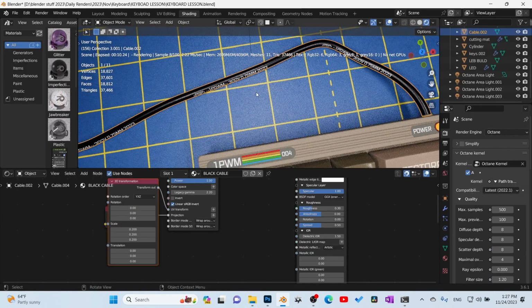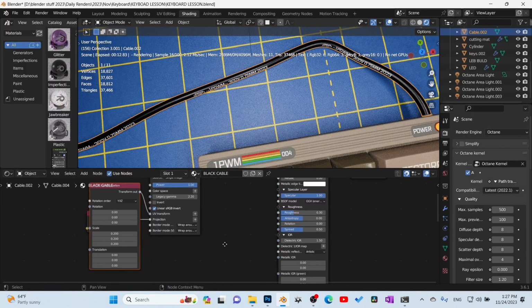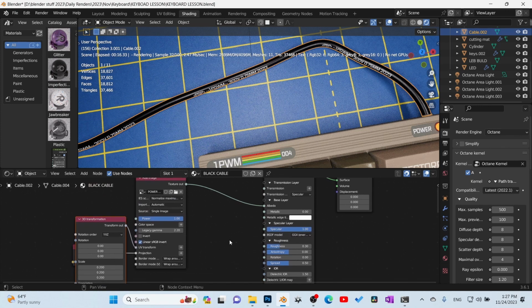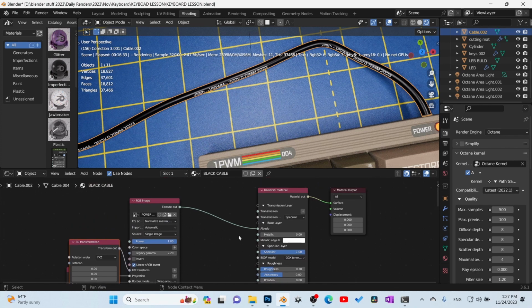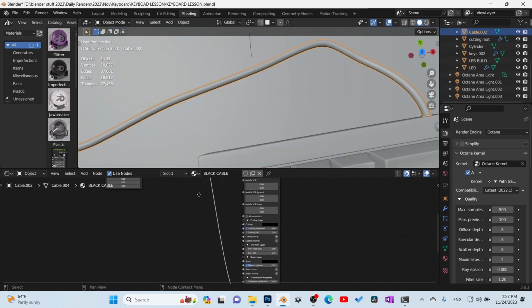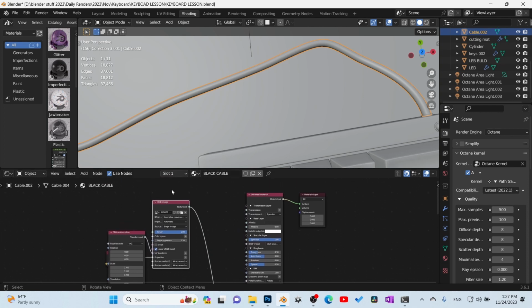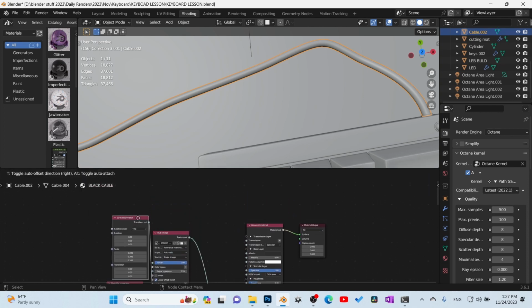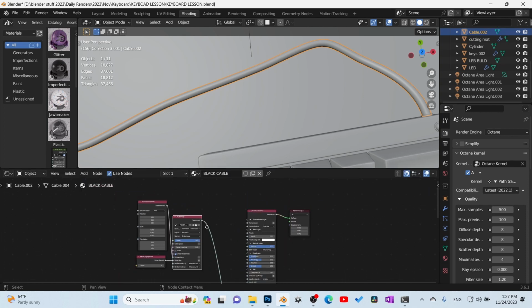Now you could leave this like that if you really wanted to show it off, but I'm going for more of a real light, and it's actually black and it's embossed, right? So what we do is we just use this here so we can see it, and then we'll plug this into the bump. And then while I'm at it, I'm also going to add in just a little bit of a roughness map so we don't have it perfect. Go ahead, Shift D, duplicate that. I'm going to bring in an imperfection map.